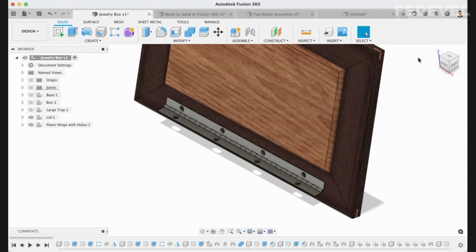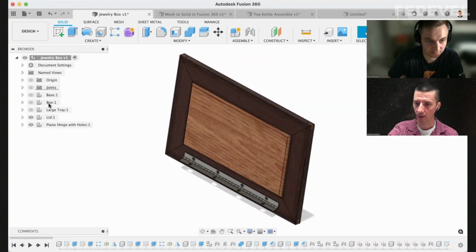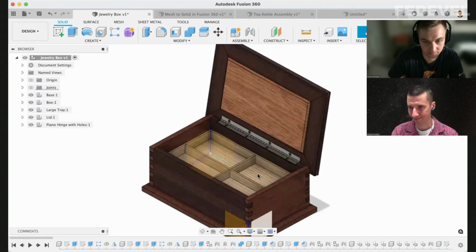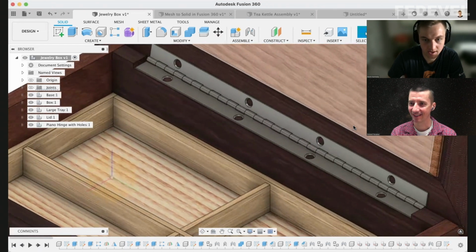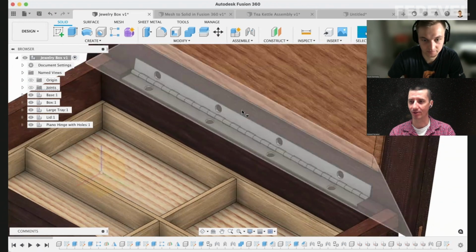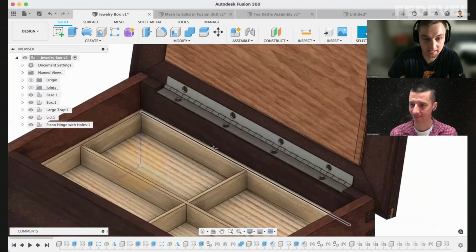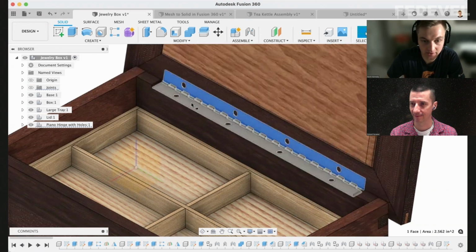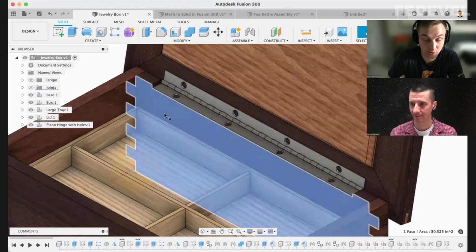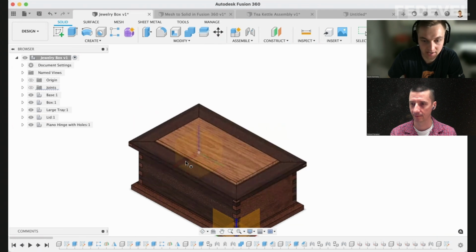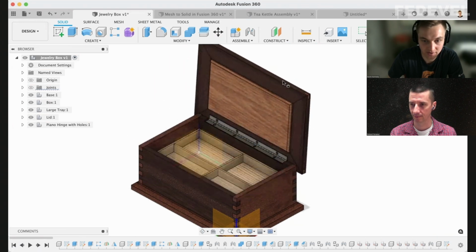Okay, so you glued the lid on the one part of the, I don't know how it's called, hinge, and it will then automatically move together with the hinge. Yep. So I basically applied a rigid joint to glue or screw it to the lid. And then the other flange, I did the same to the base or the box here. And so just by doing that and then setting those joint limits, I'm able to set this up to actually show this kind of realistic thing.